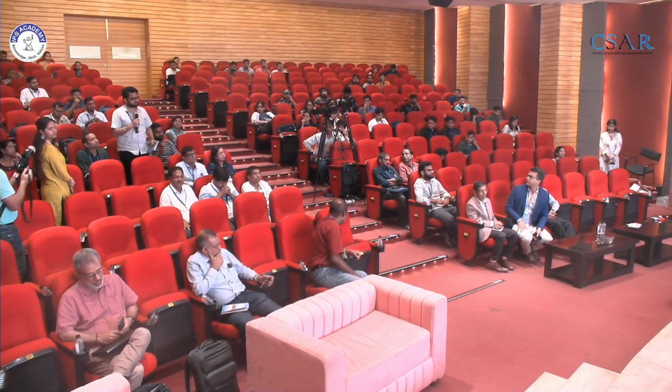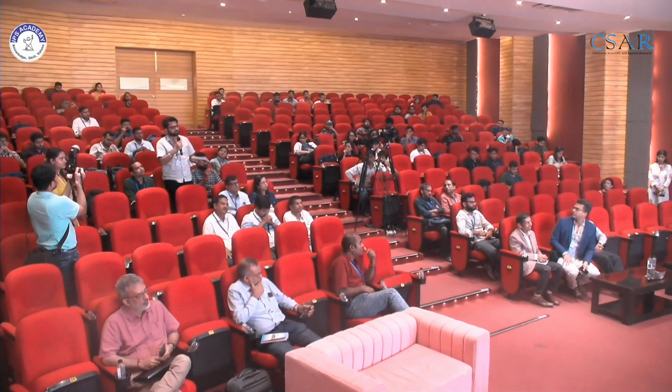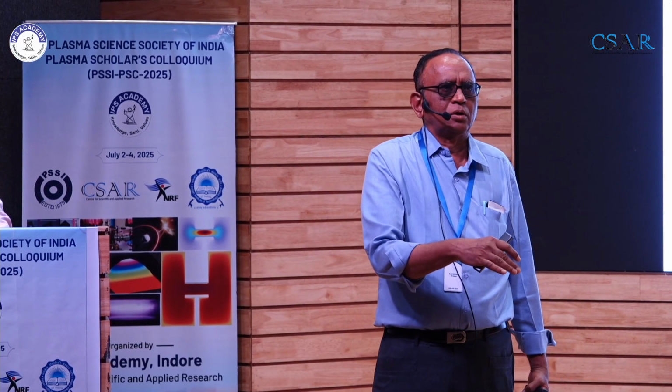One of my questions is, can we use a microwave ECR source for diamond deposition? In principle, yes, but no. Because the operating pressure in the microwave ECR source is 10⁻³ to 10⁻⁵ torr. And you need basic decomposition of all these species, carbon, methane, and hydrogen. 99% hydrogen, 1% methane. And this has to get decomposed into elemental carbon, carbon-containing radicals, atomic hydrogen, and all those kinds of things.